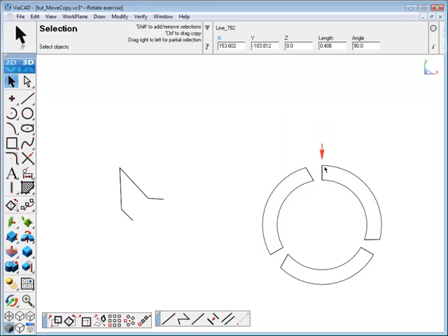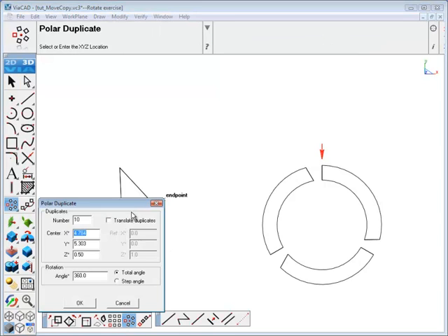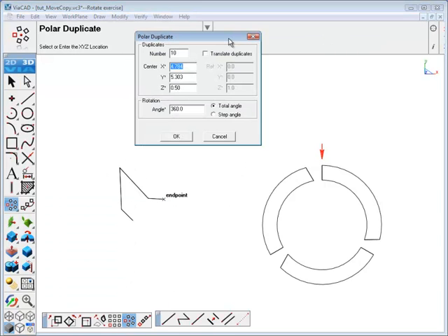and there are yet other ways to rotate. You'll notice that both linear or rectangular arrays are available, as well as polar, which are circular arrays. So we'll choose the Polar Array tool. This allows us to define a center point and create a circular pattern around that point.